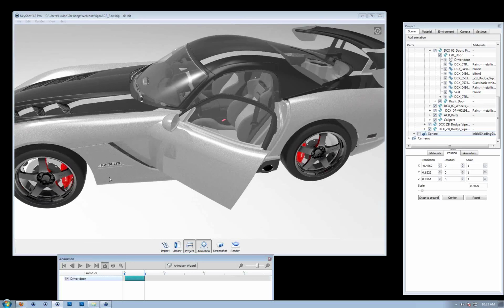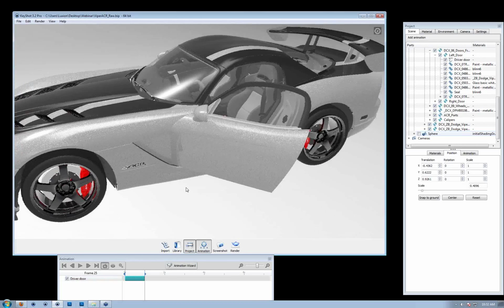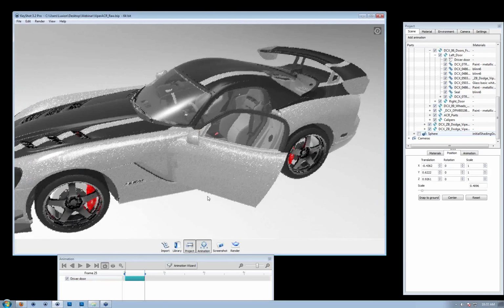We actually made it a point to not give you a completely free pivot point manipulator. It's something we might do in the future, but in designing this animation system, I was drawing on experience from another animation system, and it kind of defaulted the user into trying to customize the pivot point, and it just isn't right. It's not a good way to work. It's better to think ahead while you're modeling, if at all possible. Think ahead while you're modeling for animation. I understand a lot of our customers, someone makes the model and then you're kind of given the model to render, or render an image or render an animation. So that becomes a little less realistic. But so in that case, if you're forced to customize, you can do it with a separate model.